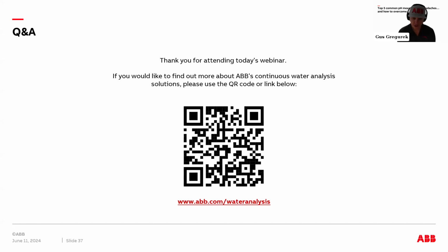Yeah, that's a good question. And the answer, I guess, is it's very dependent on the application and the sensor. So it depends on if the drift is related to a reference issue, whether that be an impedance change on the reference wire, like Nick talked about, the poisoning side of it, or if the drift is caused due to a depletion of KCl, or if it is caused due to an issue with the glass electrode, the measuring side of the probe. And so you'll see drift go either direction.